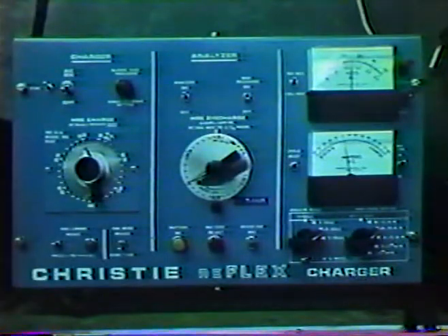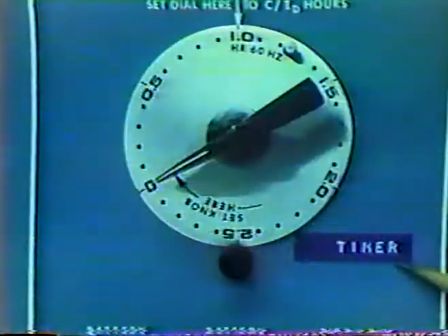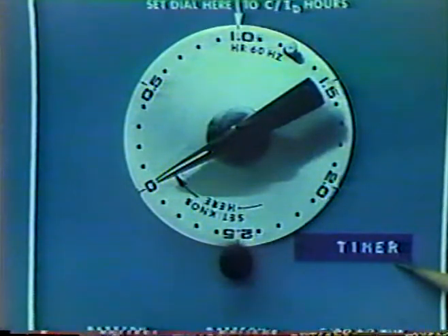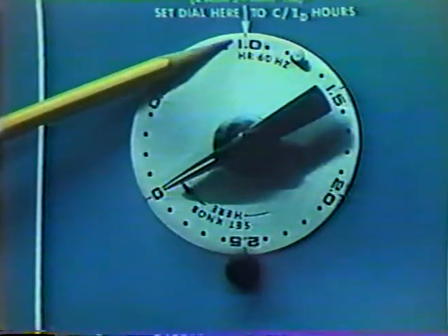Charging equipment may be of the constant voltage or the constant current type. A built-in timer controls the charge and discharge cycles. Load banks control the discharge rate. Some charging units have built-in shorting circuits for shorting individual cells or for simulating starter load on the battery.